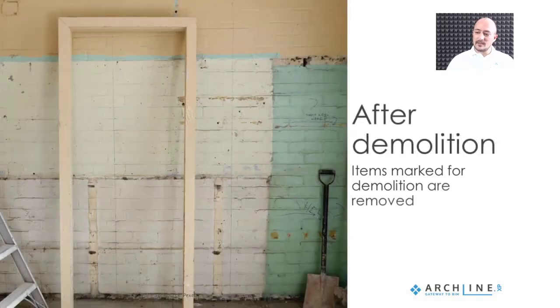After that, the software is able to, well, this is actually a phase, but it is not something that you draw. It is just a consequence of demolitioning, removing things from the building. So the third phase that the software can represent is the phase where all the things that you marked for demolition are not even in the design at that phase.